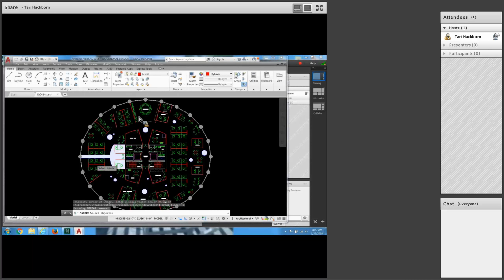Okay, so let's do what it says to do. Select the furniture system indicated, this one right here. Just click it. The whole thing is one item, so we can just click it and press Enter. For the first point of the mirror line, type 0,0 and enter. For the second point, I should still have ortho on. Come straight out to the west side of the building here and click a point to the left of the building, it says. Okay. And then press enter so that stuff will stay there. Otherwise, it'll disappear if I don't press enter.